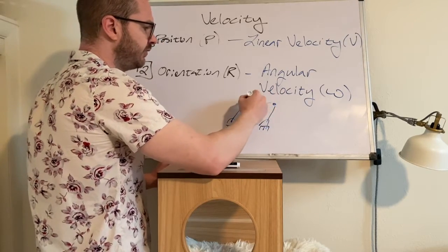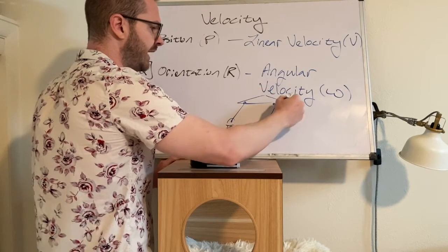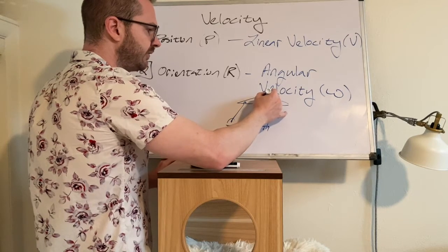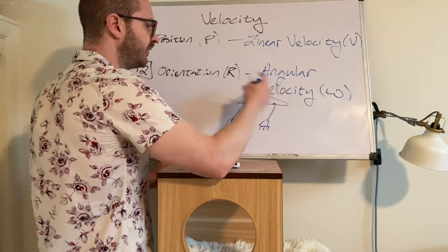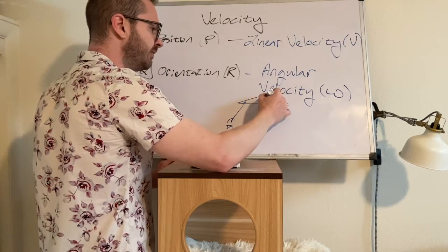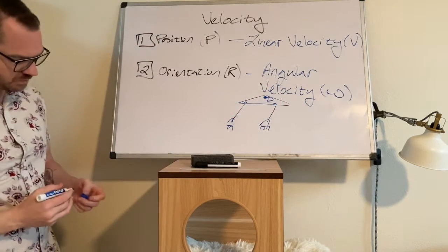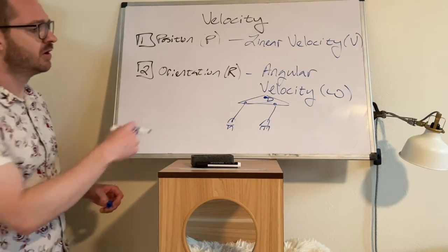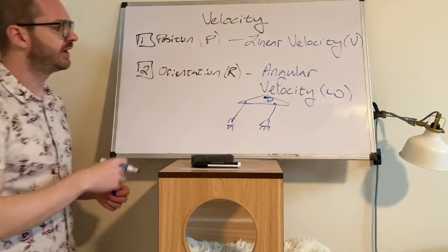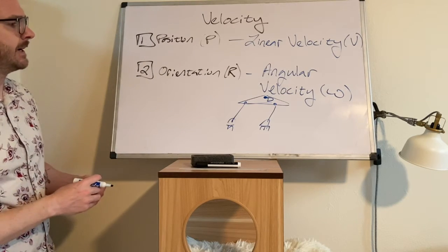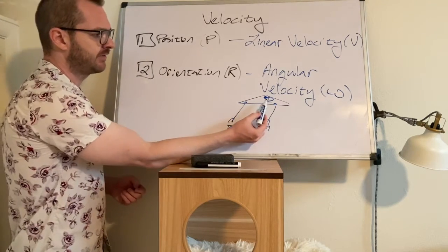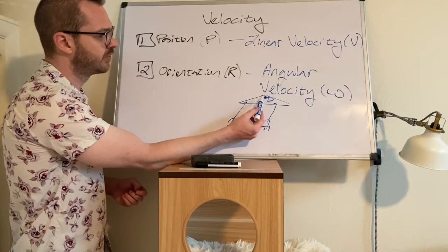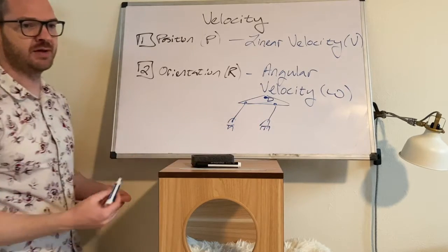And attached to this coupler, which could have some kind of unique geometry, is some other point of interest, let's say point D. And I ask you questions about point D. I could say, give me a position vector to point D. Give me the orientation, the rotation of this coupler, body B. Next I could ask for the velocity of point D, or the angular velocity of body B, things like that.